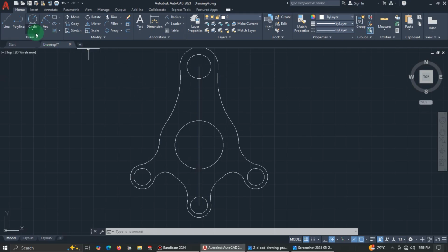So how do you do that? Just pick your circle, that is center radius, locate the center, and then click here, and then enter 6. Okay, good. Now from here we need to trim, so let's trim this side. Now we need this ones 6 numbers of this.